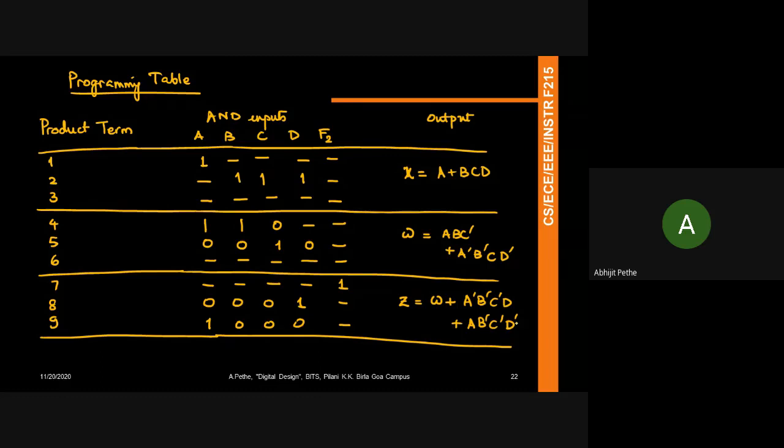So always remember that the minimized expression may not necessarily give you the best way to implement it. So ensure that you look at all possible ways of looking at the Boolean function, and that will help you implement it in the given size of the PAL or PLA.